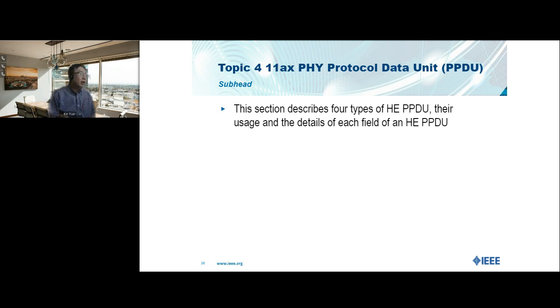This is one of the heaviest parts of this PHY training, with a lot of details, but they are the most useful ones. We'll talk about the 4 types of HE PPDU defined in 11ax, and the usage and details of each field of the HE PPDU.